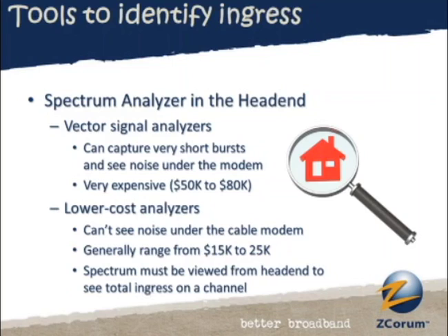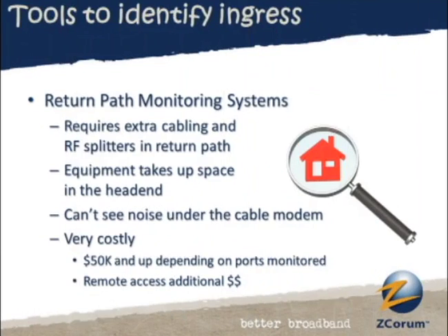Yeah, exactly. And then you've got return path monitoring systems. These are nice. These are pretty powerful. There's a lot you can do with them, but there's some downsides to these, right? Yeah, and I won't go into names because I think everybody is familiar with the names that are out there. But these really sound great, and if you diligently use them the way that they're designed and keep up with additions to your CMTS, you always add ports onto the return path monitoring tool, they're actually very effective. My complaint about them has never been that they work or they don't work, because they absolutely do. The problem is it's space, it's cost, it's training.